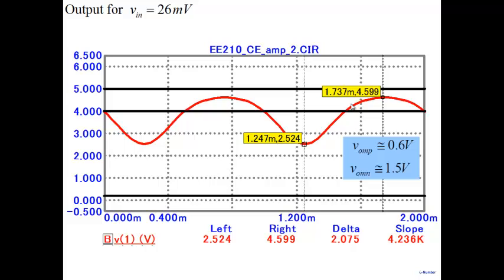Because two people can say, for example, I have a peak to peak voltage of 2.1. So you can say, well, I have a peak to peak swing of 2.1 volt. Another person says, I also have a peak to peak swing of 2.1 volt, and the two can differ a lot. This can be 2.1 volt peak to peak with, let's say, 10% or 50% harmonic distortion. Another one can be 2.1 volt peak to peak with 1% harmonic distortion. And these are two very, very different things. So saying what is the swing is incomplete. You also have to say how much harmonic distortion you are getting.